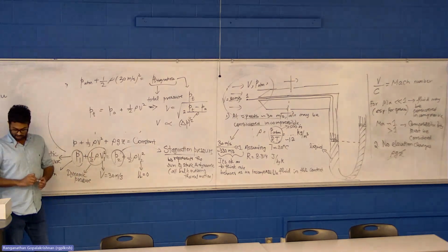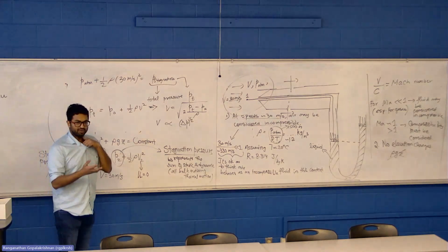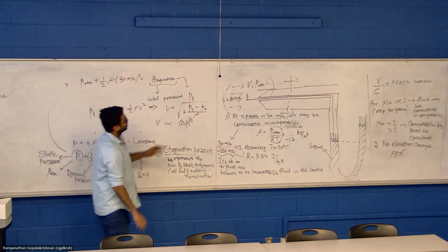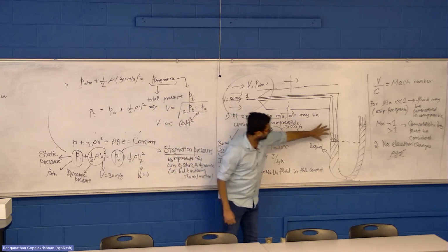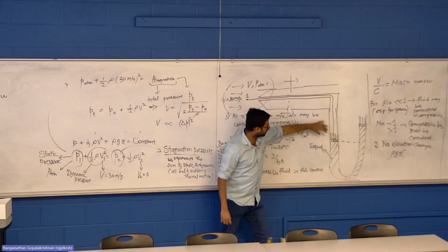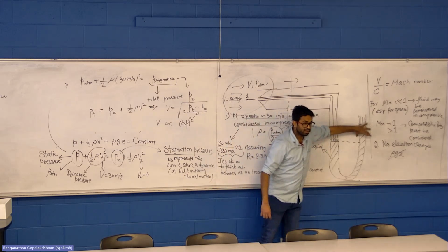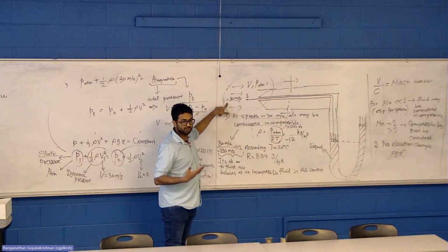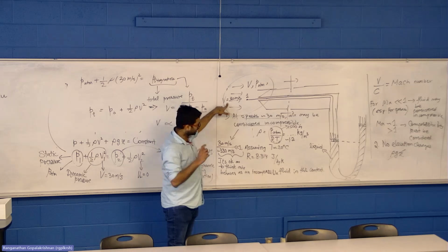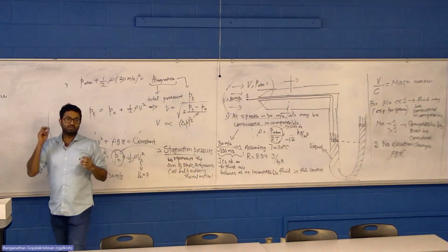Here's where you go from just knowing the physics to becoming an engineer. So this is 30 meter per second, right? If I quickly ask you for 30 meter per second, you're going to get some pressure drop or pressure difference between this limb and the other limb. If I make this velocity 4 times bigger, what will be the pressure drop or pressure difference if the velocity were 120 meter per second, what is your quick answer?